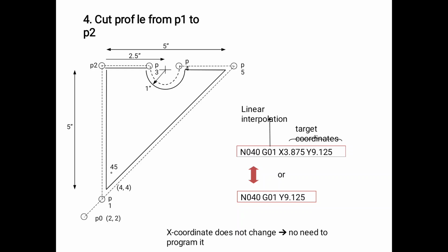The profile is cut from P1 to P2. The X coordinate does not change, so there is no need to program it.